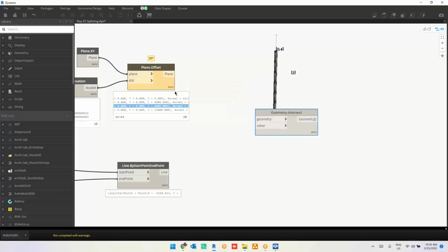Okay. So the first geometry always has to be what it has to cut. Remember one thing, geometry, not only for intersect, not only for union, not only for difference. For union it doesn't matter. When it comes to intersect or difference, you have to remember the geometry always is what has to be cut exactly. So the line has to be cut with these planes.